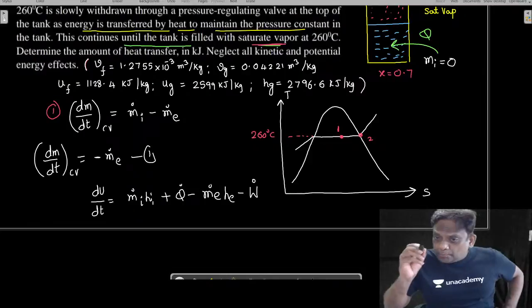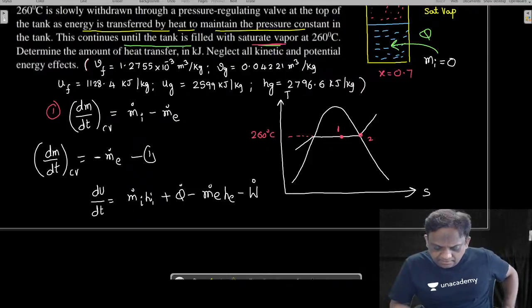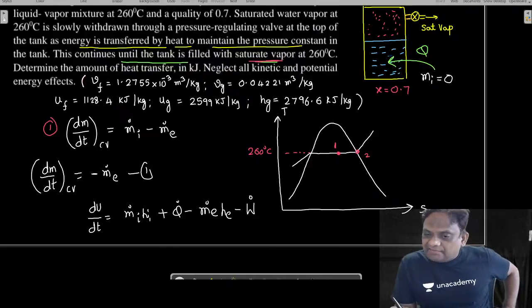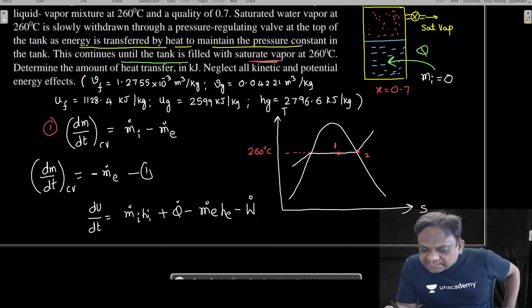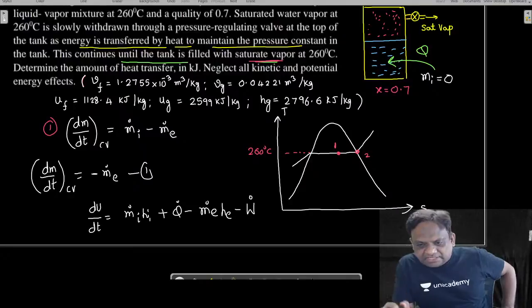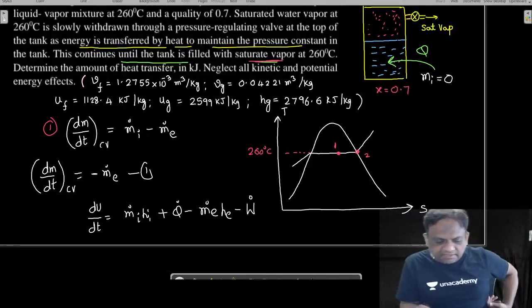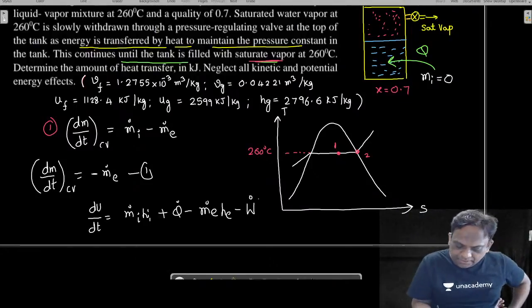Now I'll ask a question. Is this tank developing any work? Neither is there paddle wheel work nor any other. So can I put this work as 0?